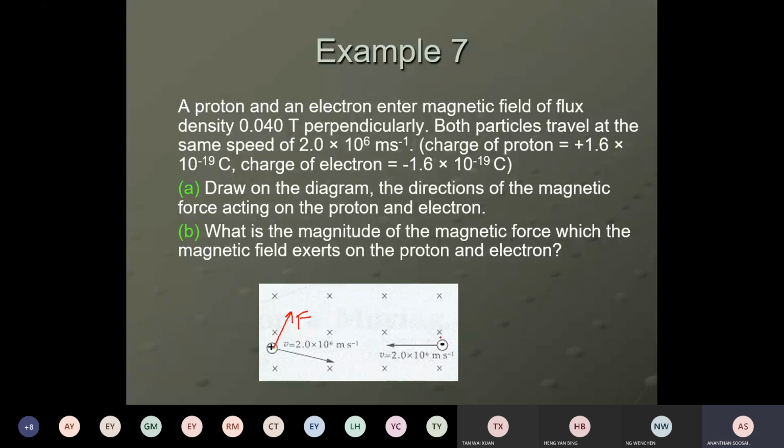Okay, negative. Which direction is the force? FBI. Magnetic field is into the page. I, the current, is to the right or left? The electron is moving to the right. The negative charge is moving to the right. So current should be to the left. The electron moves to the right, and current should be to the left. So the Fleming left-hand rule is pointing the current. So put the current correctly to the left, FBI. So the force is still upwards. Yeah, good, correct.